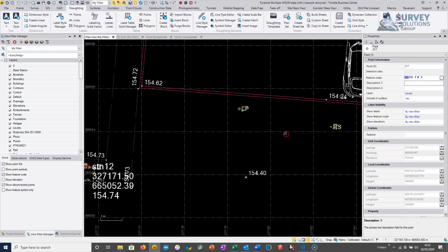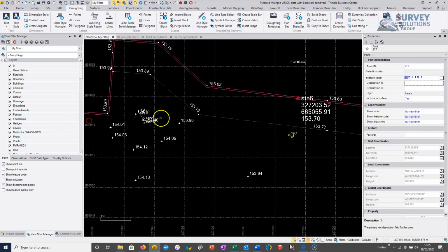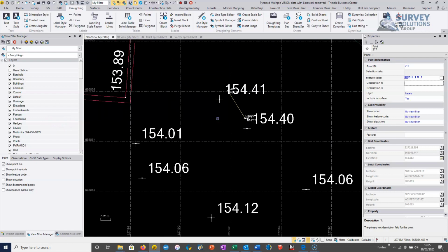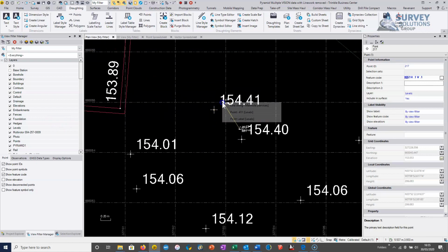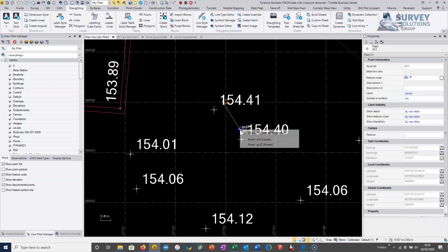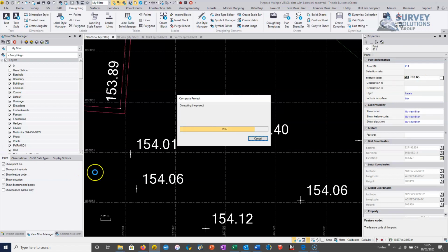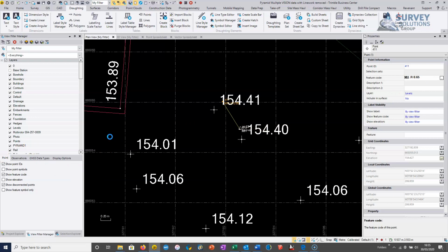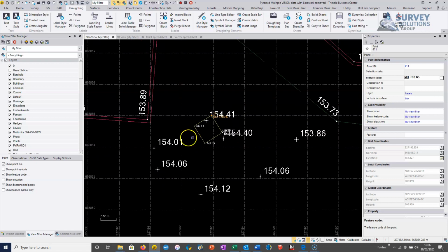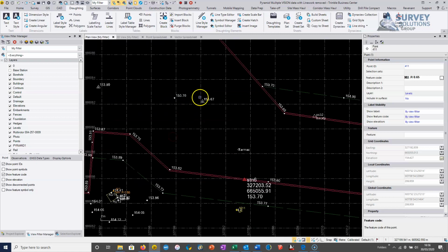So generally, we go through the whole project, reviewing where there are some coding mistakes. I see another one here. If I click on this individual point, 611 manhole rectangle, and then 612 manhole rectangle, the rectangle does not have a size. I can go in there and just update the size, hit F4, and once again, that's going to be much faster to do by purely changing the code. So the first thing that we generally do is go through and make changes to the codes.